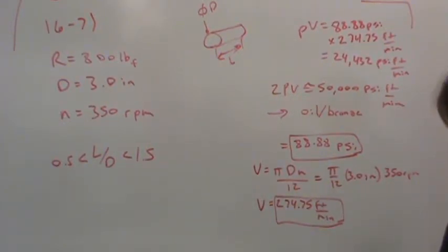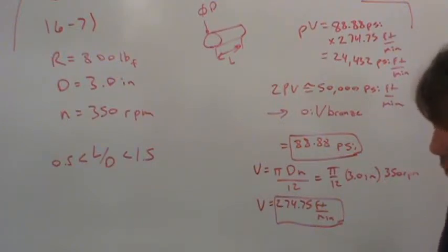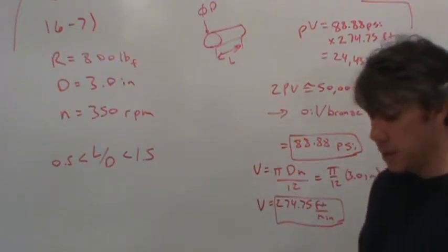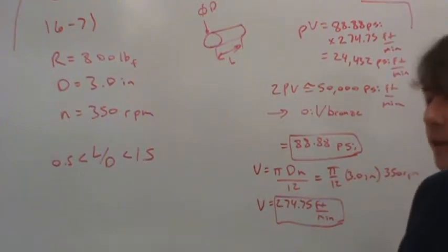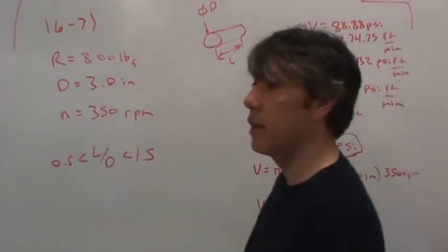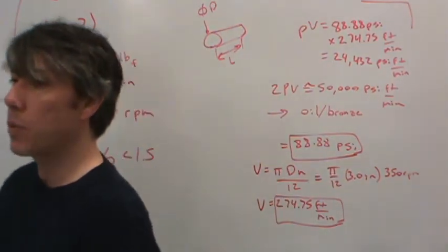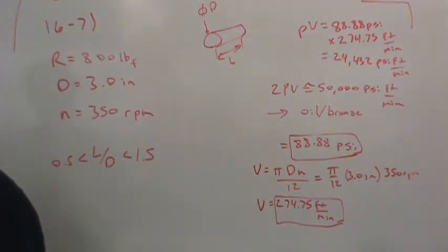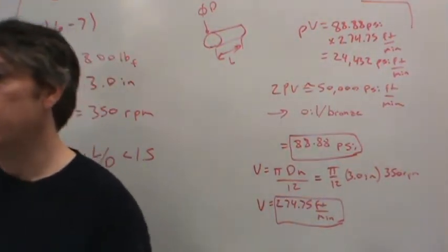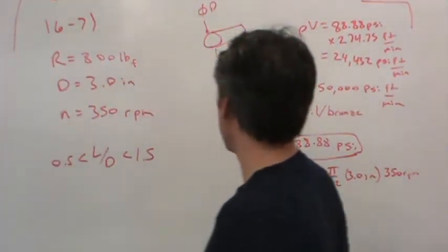Okay, specify material, we did that. Complete the design of the bearing system considering diametral clearance, lubricant selection, lubricant supply, surface finish specifications, thermal control, and mounting considerations. Often the supplier of the bearing material provides recommendations for many of these design decisions. Basically, what your author is saying there is you're not done because there has to be some clearance between the journal and the bearing. But at this point, the material dictates those things. And so you go to the manufacturer of the material and ask them what you do.